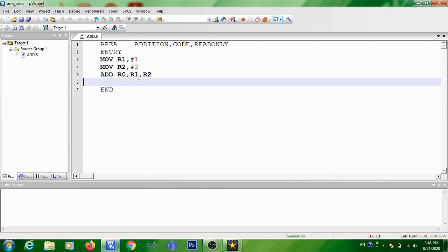What is the short jump you are adding? Stop. Then you can give space or tab. Now I have given space. B, tab, stop. So stop, B, stop. That means you are adding a short jump. You are instructing the program counter or processor to execute this line infinitely.